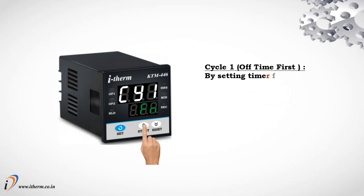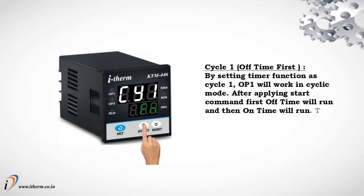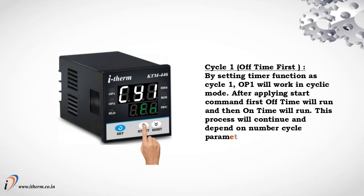Cycle 1. Off time first. By setting the timer function as cycle 1, output 1 will work in cyclic mode. After applying the start command, first off time will run, and then on time will run. This process will continue and depends on the number cycle parameter in the user list.